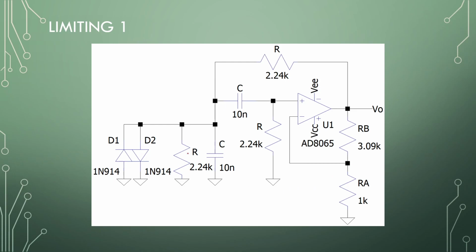So with this input resistor grounded, we will have oscillations, but our output will go to the saturation limits of the op amp. So one method of limiting is putting two diodes across this input resistor, which will limit the input here to plus minus 450 millivolts roughly. And on the input we will have some losses. Multiply that with our gain over here and we will have an output of plus minus 1.5 volts at the output of this oscillator right here.